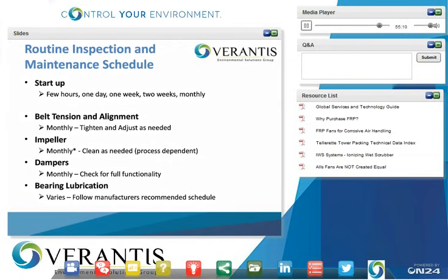Dampers should be checked monthly as well for full functionality, making sure they're able to open and close completely. There are a lot of systems that have automated dampers that would involve motors or sensors. These should also be checked because it's very possible that a motor can burn out or a sensor goes bad, and a damper could either close and remain closed or open and not close when needed and cause problems. And then bearing lubrication, that will vary. It depends a lot upon how often the fan is operating. Again, following the maintenance schedule's lubrication recommendation is important.